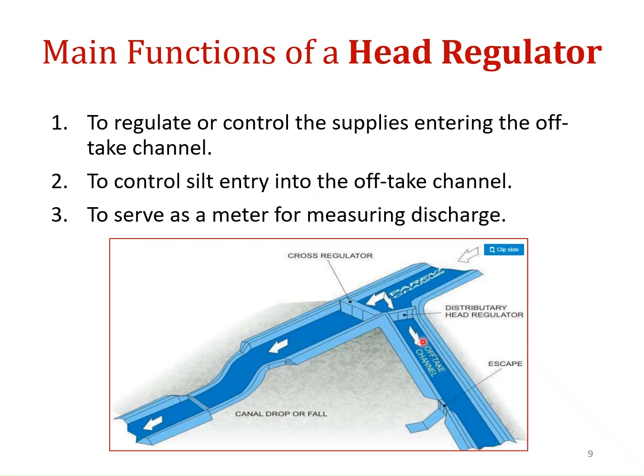In some situations the parent channel has higher silt if there is some rain in the upper reaches. So the silt quantity is higher, and you don't want the silt to enter the off-taking channel because the off-taking channel is smaller. If an excessive amount of silt enters it, then the cross section may get compromised. So you control it. You can close the gate when the silt is higher in the parent channel.